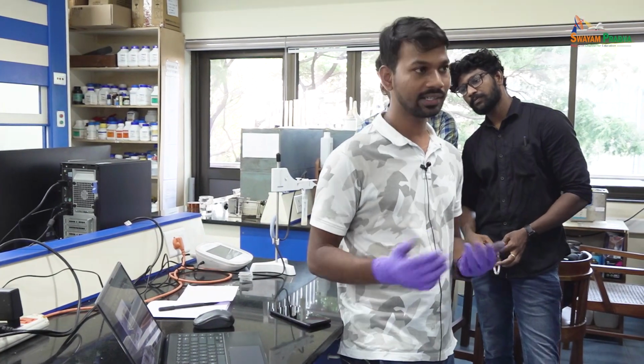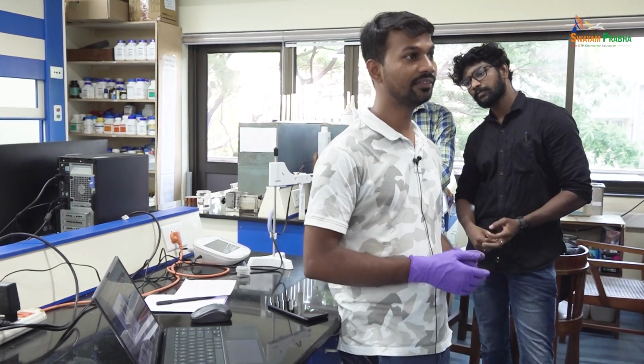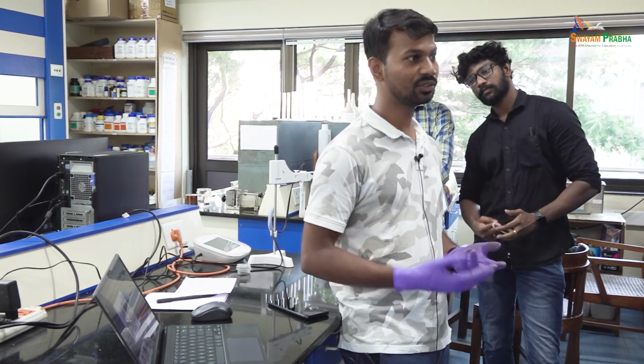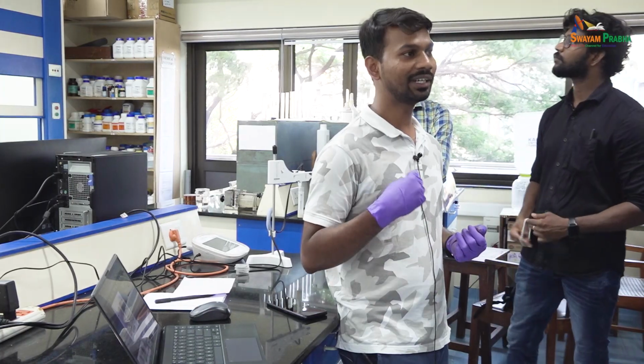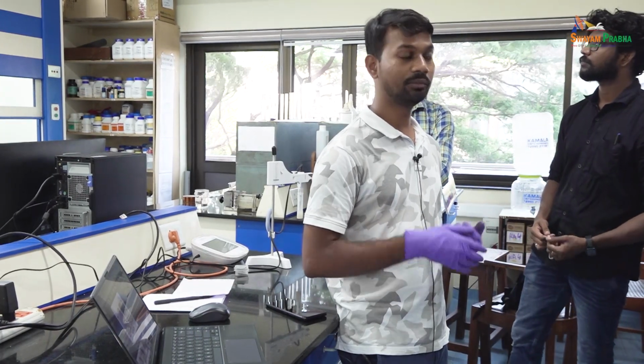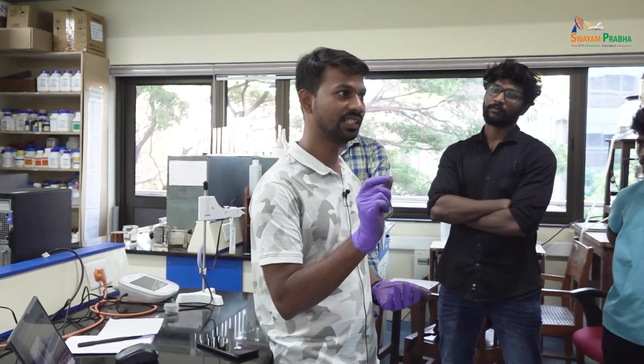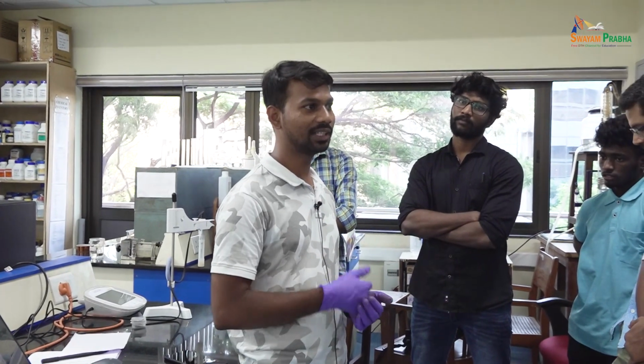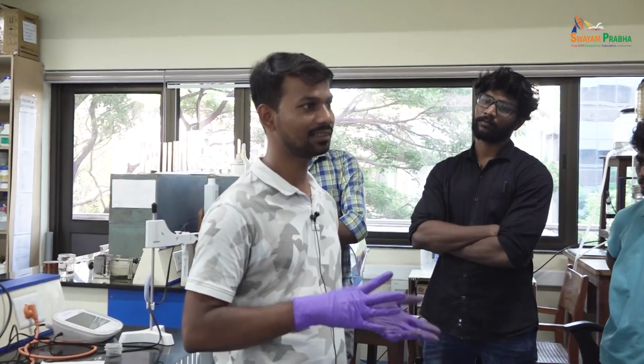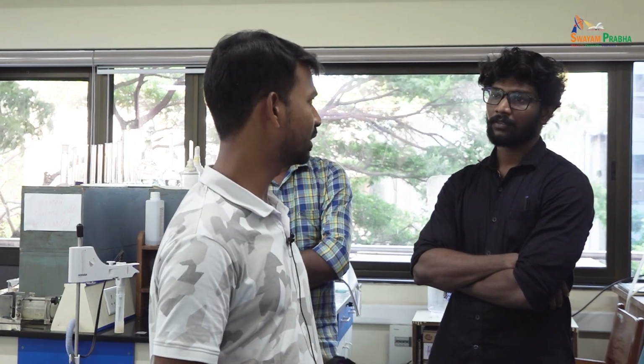Grooving on graphite is very difficult and very expensive, and since it is brittle it may crack if you are not taking care. In the case of metal we can stamp it, and also use very thin sheets for bipolar plates. But the problem with metallic bipolar plates is corrosion, so that is what we are studying. On which solution are you doing it? Generally I am using aqueous electrolytes only, one is urea based, another one is acetic acid based.